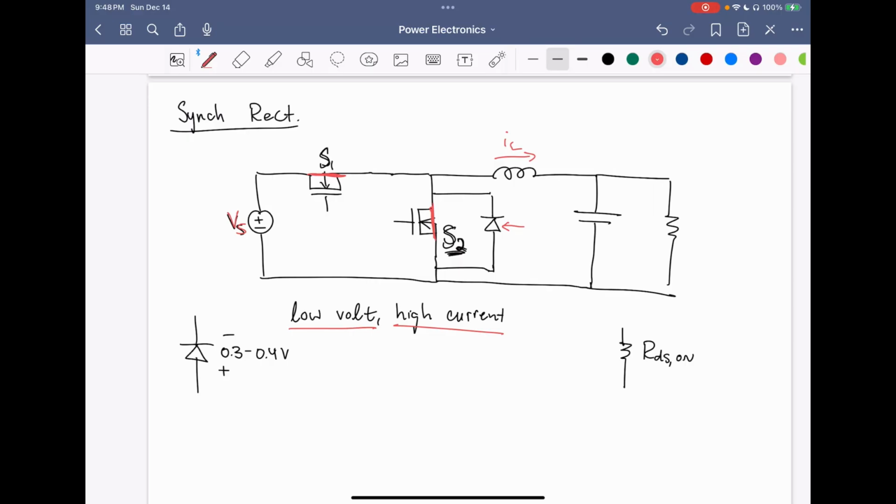However, with higher switching frequencies, we also get increased power loss in the switches. And that means that with more power loss, more heat is produced. So therefore, we might need a larger heat sink, which then offsets our reduction in size of the inductor and capacitor. So that's one trade-off to keep in mind as well during the design process of the buck converter.